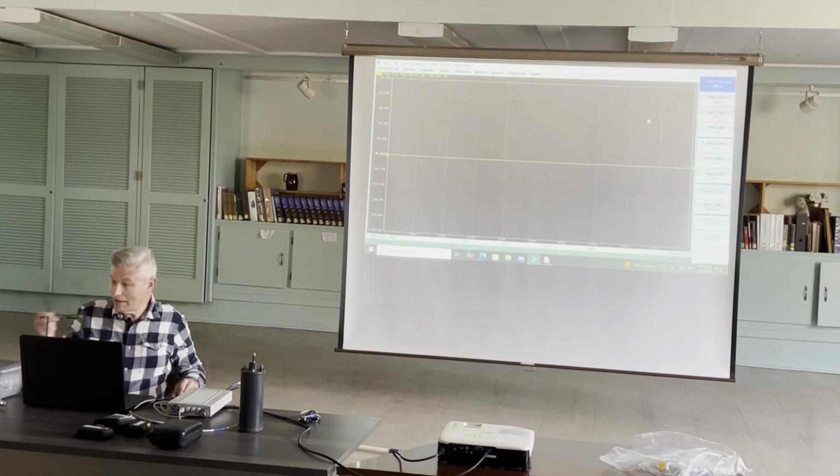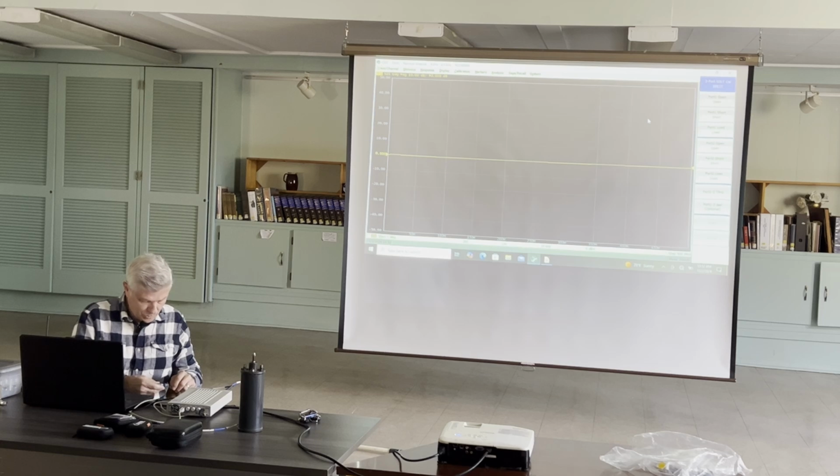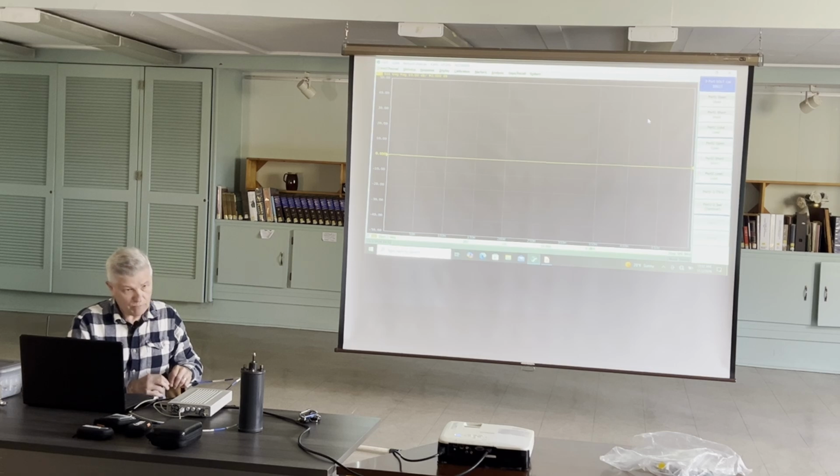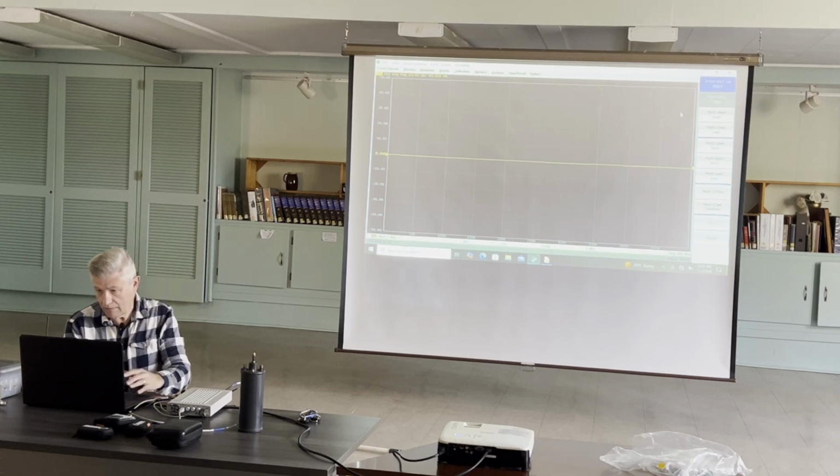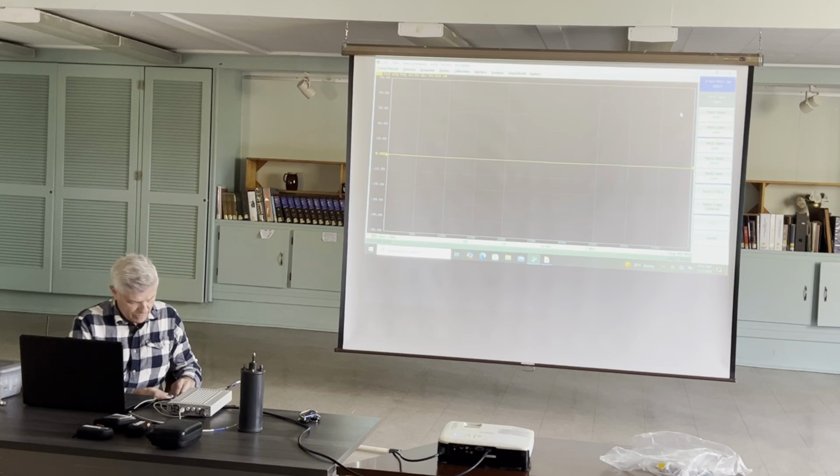And for this, I got to take my glasses off because I can't see anything up close with those on. So we'll start with the open circuit. And what we're doing is we're just telling the analyzer, hey, this is a perfect open. Okay, once we get that check mark, we're done with that. We can do the short.